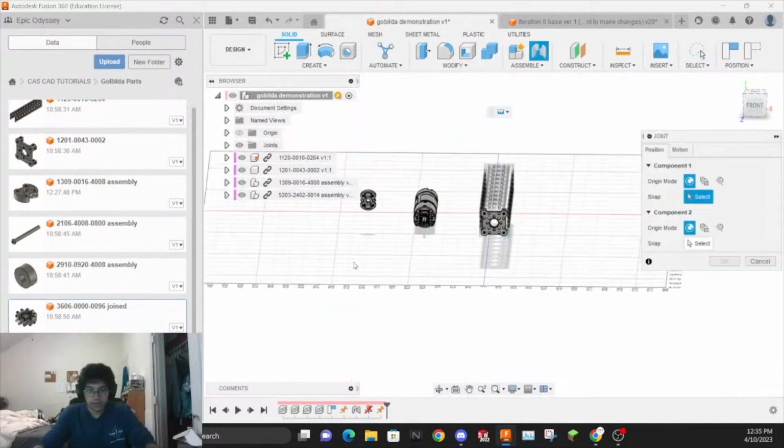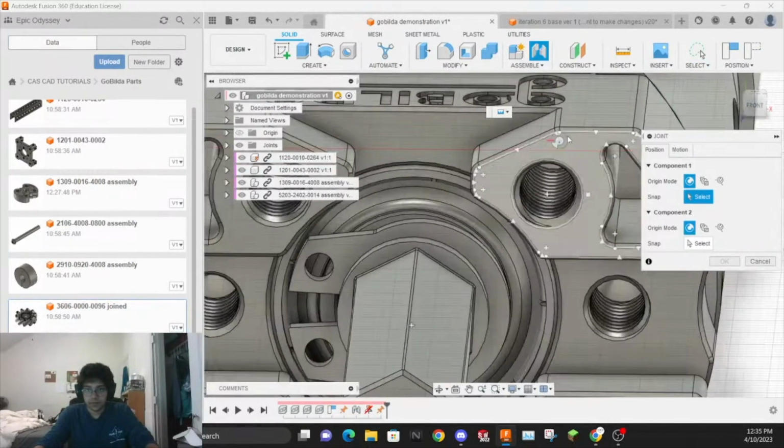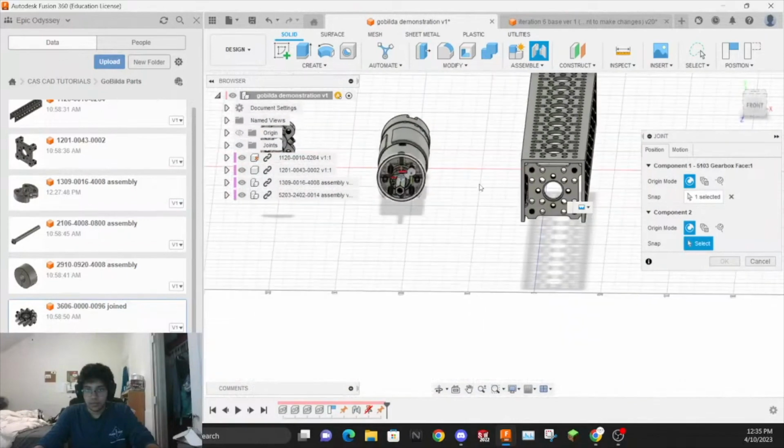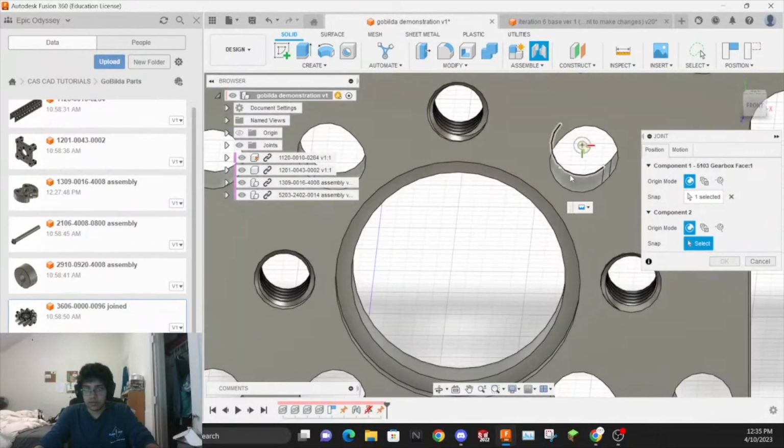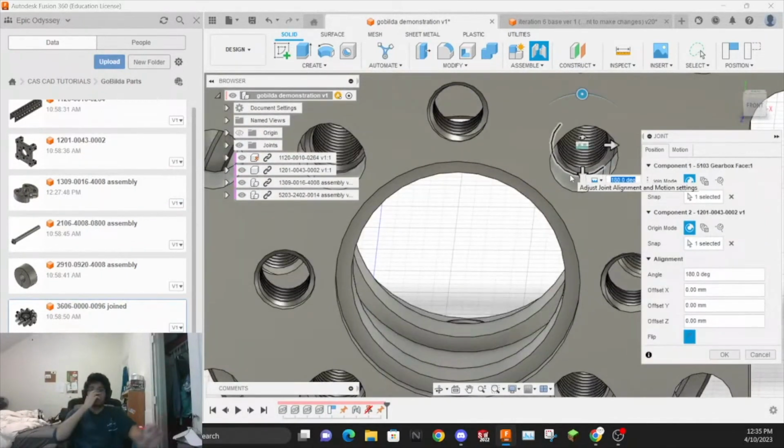and then select the threaded holes, and then insert them into the non-threaded holes. Here's something very important that you need to know. Do not put two threads together. I'm begging you, don't do it, because you're going to ruin the thread and you're going to ruin the part, right? So what I really mean is